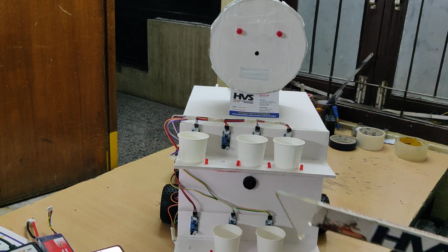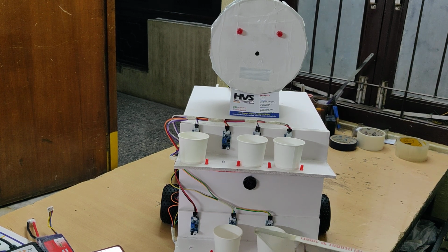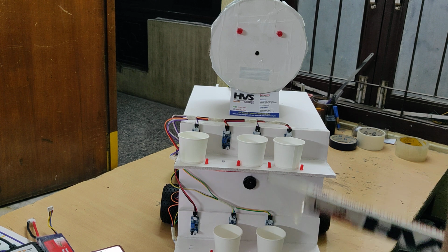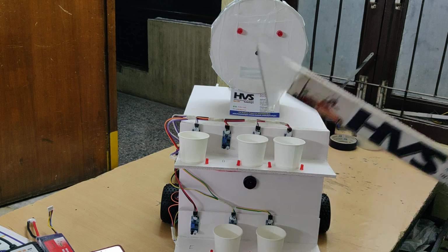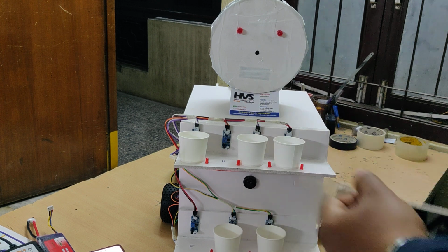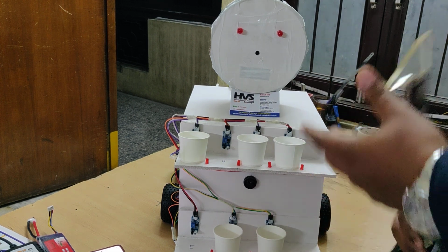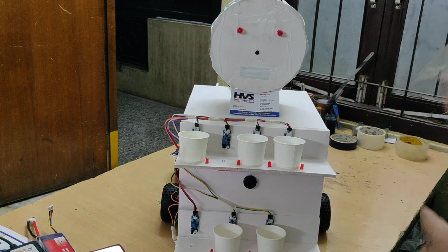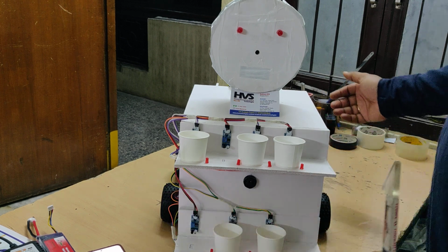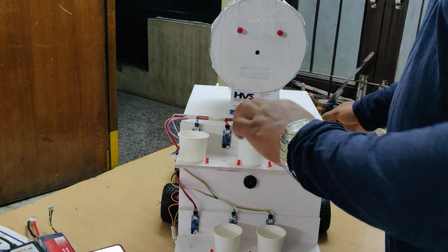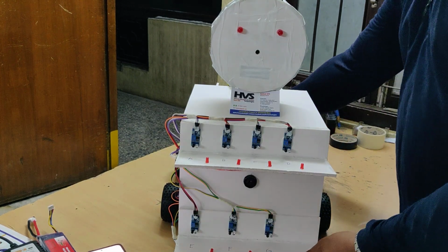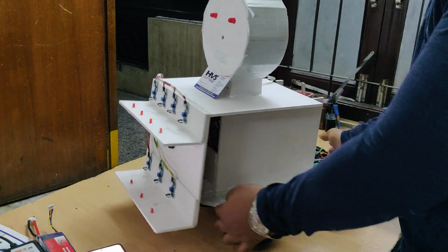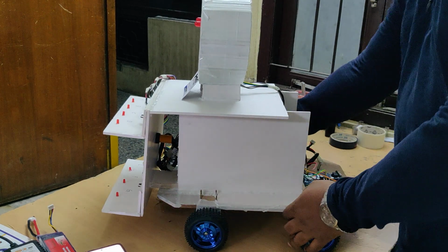The encoder consists of a Hall effect sensor. Whenever the DC motor shaft rotates, it will inform us of the pulses. Based on the number of pulses, we count the number of centimeters the wheel has covered till now. Here we have placed a total of 4 DC motors to make this robot a 4-wheel drive, and the DC motors interface to our Arduino Mega board.